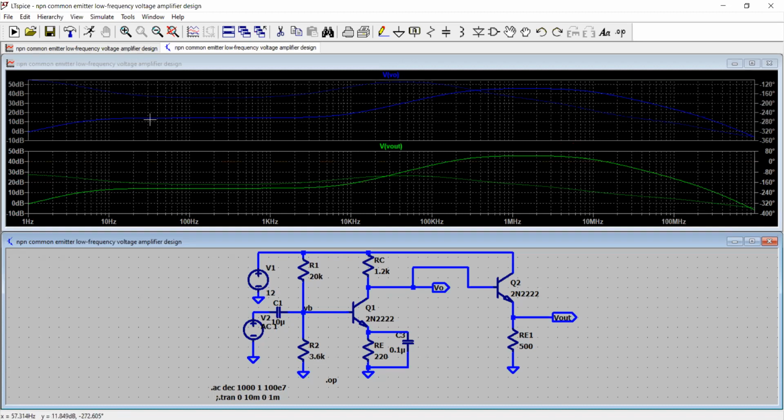Use like 10 dB because your signal is about 1 kilohertz. In the time domain we had this, so gain was about 5 times. So 20 log of 5 would be your magnitude, right? So it's about 10 dB. That makes sense.